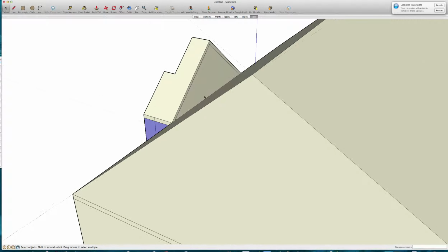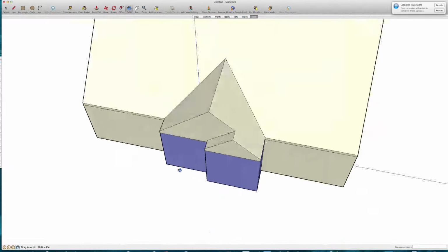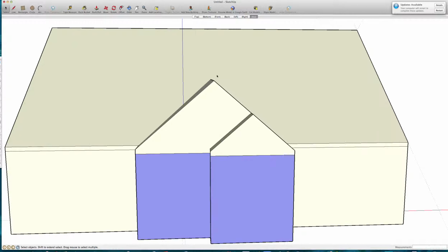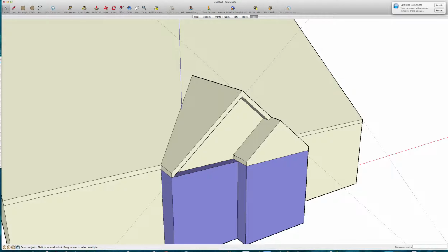Okay. That also enables me to pull the turn gable into this slope. I'll select everything and hit the I key for intersect. That'll give me my valley lines. I'm going to come around to this front, and I'm going to use some guidelines to create a 6-inch fascia board on these two rakes. That's going to enable me to push this area here back 1 foot, and then I'm going to pull a 6-inch slice here so I have a matching fascia. Delete a few lines. I'm going to create a guideline here that's a 10/12 pitch.